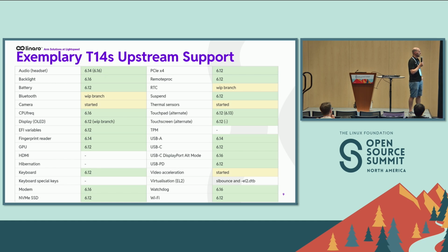RTC, I think, again, we have patches for that, how to handle a specific offset to make sure that we have the real-time clock that is sitting in there. The thermal sensors, I think we are waiting on some of the core patches for the PMIC drivers to read the sensor values out and then feed that back into the thermal system to have different thermal zones and define how Linux should react if the heat goes up in a specific area, like throttle the CPU or something like that.